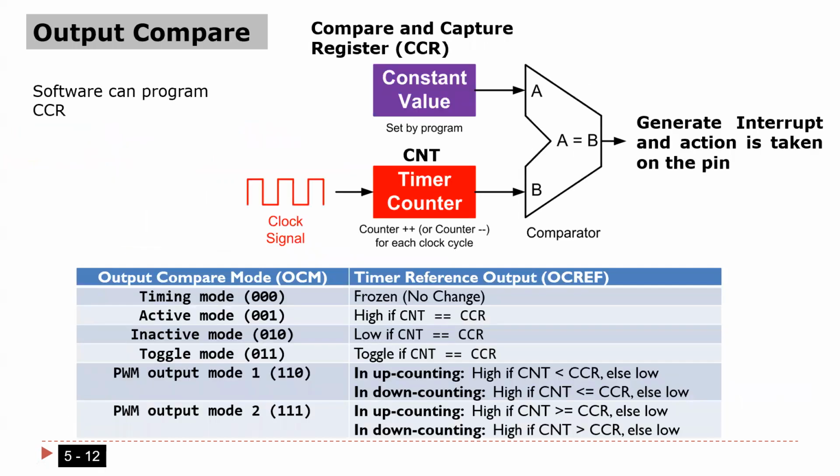Okay, so let's come to the idea of output compare. What is the idea? How does it work? This is the way it works. Look here, guys. Again, as I told you, we have a counter here, hardware. The processor does not need to increment the count by 1 or something like that. It's free running, independent of the processor. So the count CNT register should give you the current count. What is the current count? And then you have a clock here, as I told you. This is the counter, as you know. So what happens is that, look here, guys, we have another register.